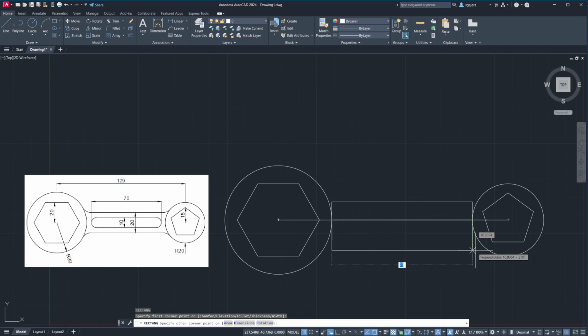To access those tracking options, you just hover over a point and AutoCAD is smart enough to know what you want to do. So here, AutoCAD knows that I'm tracking this edge right here. That's why 79 is locked, semi-locked.